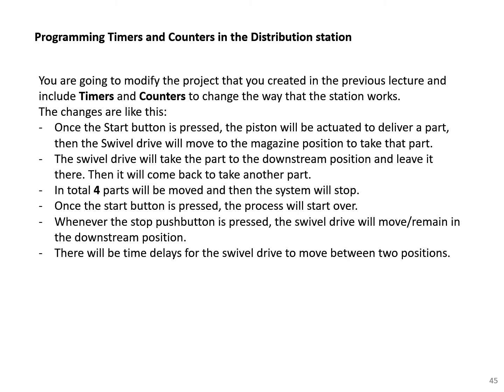Once the start button is pressed, the piston will be actuated to deliver a part. Then the swivel drive will move to the magazine position to take the part. The swivel drive will take the part to the downstream position and leave it there. Then it will come back to take another part. In total, 4 parts will be moved, and then the system will stop.